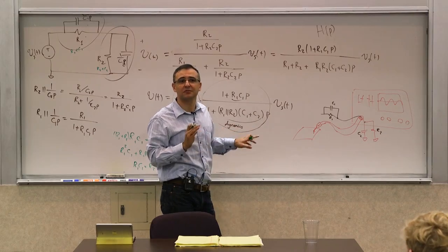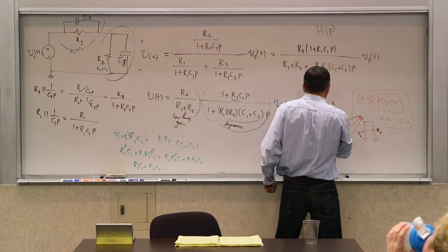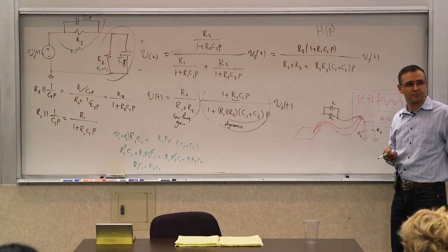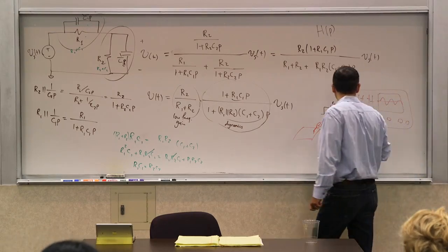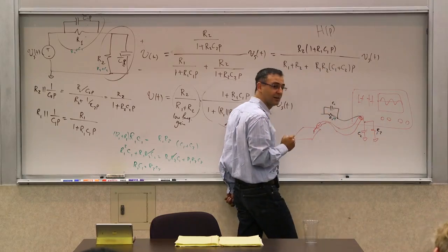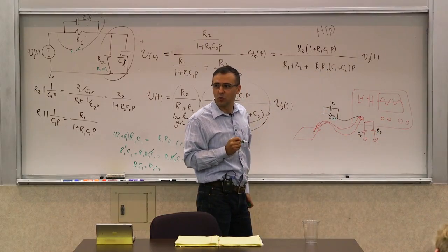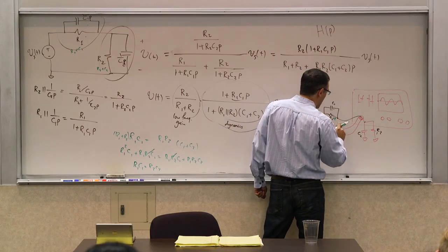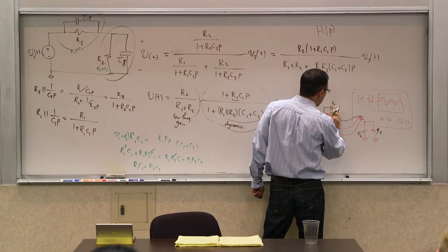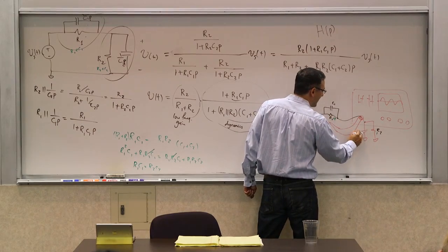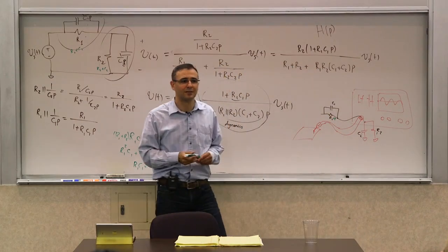So it acts like a resistive divider. So what you do, if you make this product the same as that product, and the way they do it, they make this a 9 resistor, and they make this 1. So 9 to 1. Now 9 something, 1 something. The ratio is 1 to 1. Now what you can do by putting the right capacitor here, you can actually make the effect of this capacitor disappear.